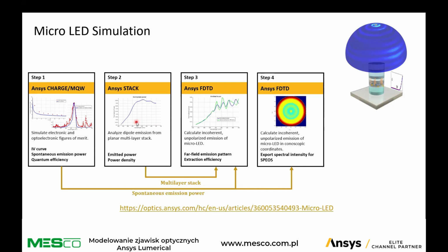the coatings, where we can get the reflection and transmission coefficients as a function of the wavelength, thicknesses, and so on, and angle of incidence. But it can also be used for emissive structures, where one of the layers is emitting light. And this is the case that we use here. The idea is that for the stack, we consider that the layers are infinite in the lateral direction. But that gives a bit of an idea. So we can optimize the layer distribution in order to get the best emission and extraction.